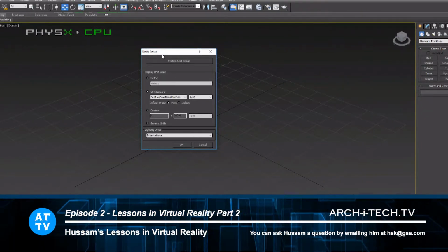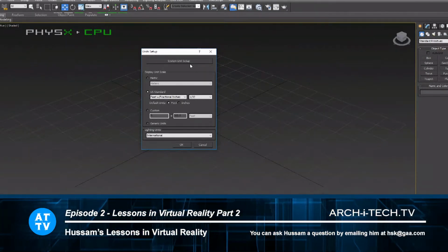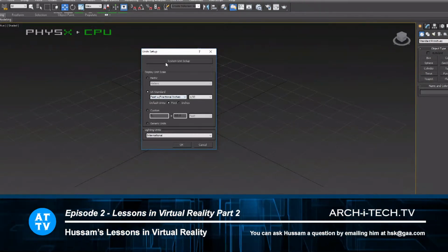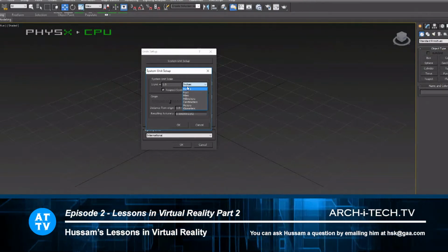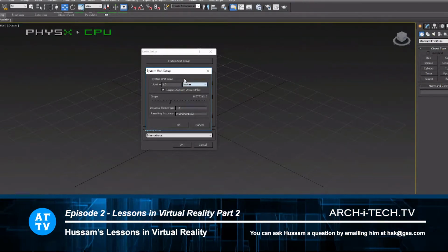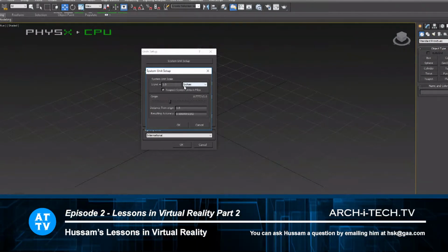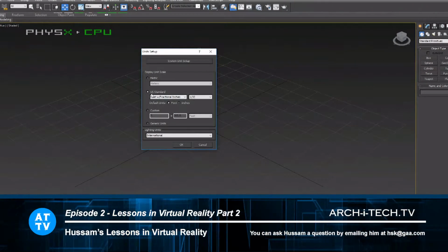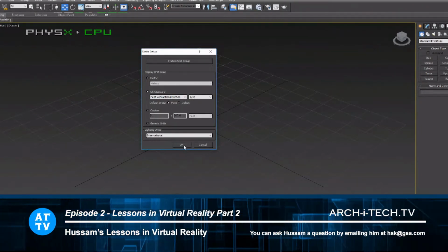And then the other thing, which is more important, is the system unit setup, because even if you work with feet or inches here, this one may show millimeter or centimeter or another unit, which is the wrong thing to do. So basically by default, 3D Studio Max will start with inches. So keep it as is, inches, and then select feet or inches from here and just hit OK.